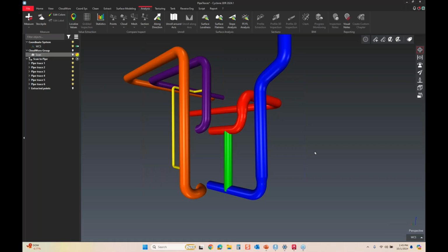All right, perfect. Next question. What method do you typically use when aligning and rotating a scan to a CAD file or BIM model? Great, another great one. So good question. It depends on how that BIM model or CAD model is laid out from the beginning. To give you an example, if I have some known points, that's my favorite method, right?